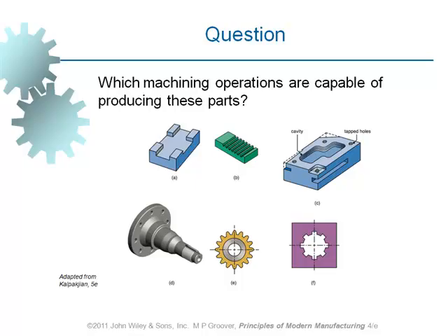We've got to make the hole first on the workpiece, then pass the wire through the hole, and then cut the material, which works well for so many processes. Particularly for making high punches and dies in press working, EDM is widely used. EDM can be used for this, but that's not the only method.